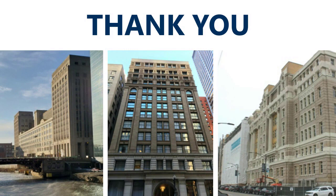Okay, next question. Do you use drones to conduct condition assessments? We definitely have. It's a good first step. It's a tool like anything else. As we mentioned, that visual assessment is exactly that. It's a visual assessment. So if there's something that we need to get up close to, where we might need to do some sounding or other non-destructive testing, a drone won't do that for us. But it certainly is a good first step. It's an inexpensive way to see the building close up.